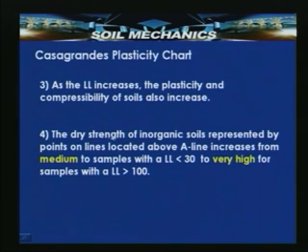So, if you look into it, here the plasticity and compressibility are increasing as the liquid limit is increasing on the chart, and the dry strength of inorganic soils represented by points above A line increases from medium for samples with a liquid limit less than 30 to very high for samples with a liquid limit greater than 100.